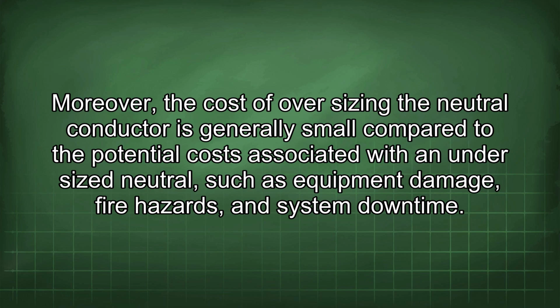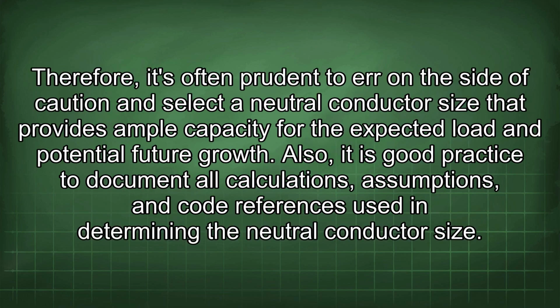Moreover, the cost of oversizing the neutral conductor is generally small compared to the potential costs associated with an undersized neutral, such as equipment damage, fire hazards, and system downtime. Therefore, it's often prudent to err on the side of caution and select a neutral conductor size that provides ample capacity for the expected load and potential future growth.